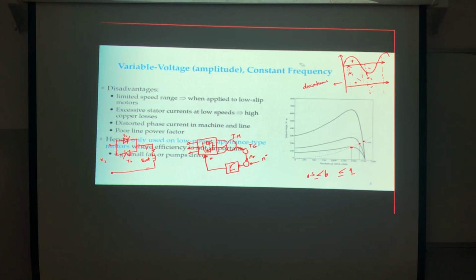So if we assume a discontinuous mode, we already proved that. If we assume continuous mode of operation, then at the positive half cycle, I'm firing T1. So this one is on, and this voltage will equal to this voltage, correct? So this is the supply voltage.